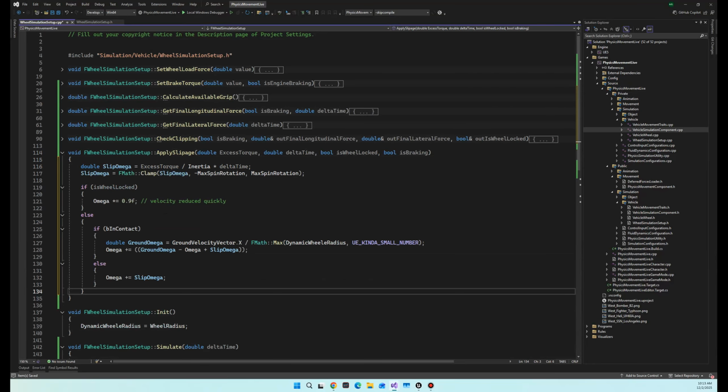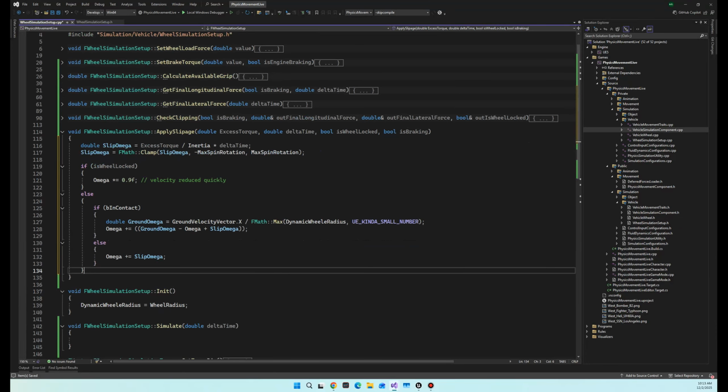We're applying grip, but we also need to figure out if we need to apply slip. A tire slipping, you might see that when we run the simulation and first start driving. If I stomp my finger on the gas trigger, the front wheels, if they don't have enough ground pressure, those drive wheels may start to slip a little bit before they bite into the ground. So that's what we're going to be calculating.